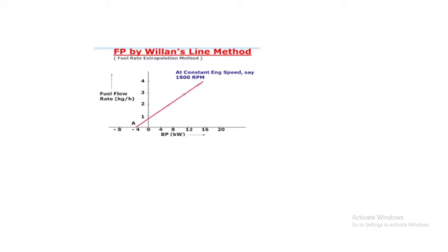The heat energy is the input which drives the crankshaft. Whatever power we obtain at the crankshaft is the brake power, and the frictional power is the loss. Whatever power we produce in the combustion process in terms of heat energy, some is utilized as useful work, that is the crankshaft power, which is the brake power, and the losses we can call the frictional power.